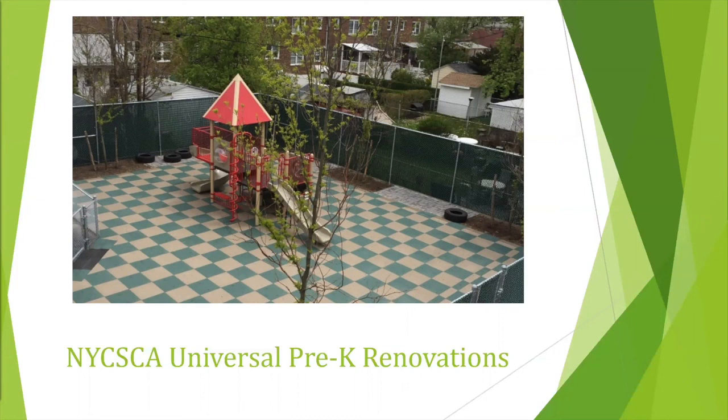And a lot of times we always wanted to make sure that they had the play space available, but that we could address the stormwater management within the site and not have to deal with a discharge to DEP. So here, the entire site is lined with trees and permeable pavers. We have small filtration systems underneath the pervious pavers so that everything from that playground site would drain. And then we're also getting the benefit of the trees for the children, obviously, within an urban environment.